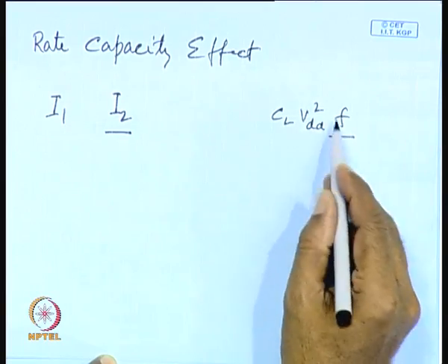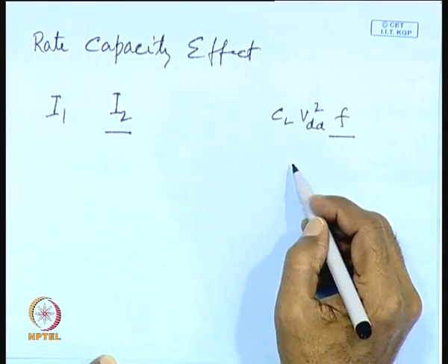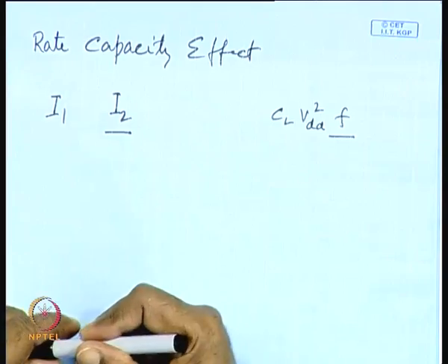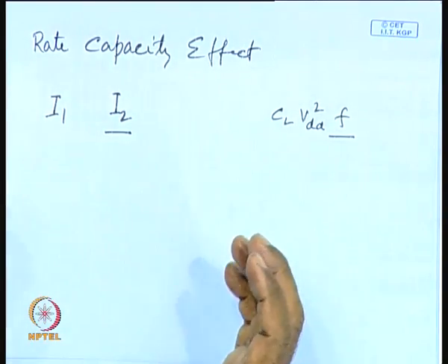So, depending on the workload condition, you can do voltage scaling. If you reduce the voltage, the current that will be drawn will be reduced, and as a consequence you can match the current drawn with the workload condition, and that in turn will lead to lesser current and longer actual capacity and larger battery life.